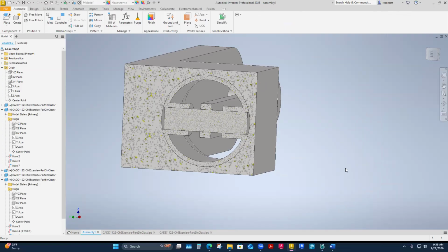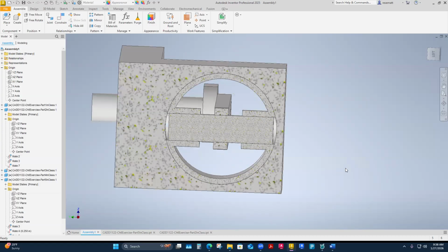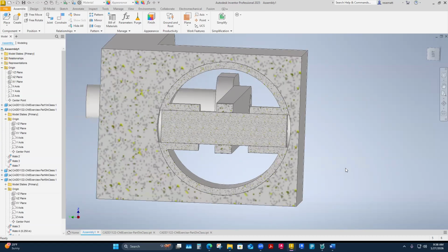You're not just creating random parts, you're creating parts that are going to work with each other, and having them designed somewhat thoughtfully will help you align them, right? And this will help me in the event that I make a 4-inch cylinder. I have a really good base to start with here. If everything is dimensionally constrained, it gets really annoying to modify this to a 4-inch size. But if I have minimal dimensions put in and more geometric constraints, then I can make changes faster to this whole assembly and not have to go back in and fine tune every little dimension that I put in.